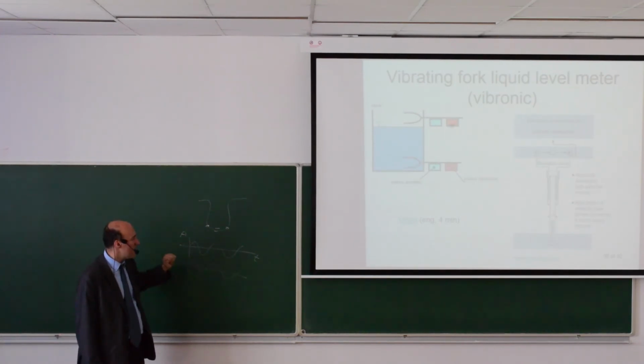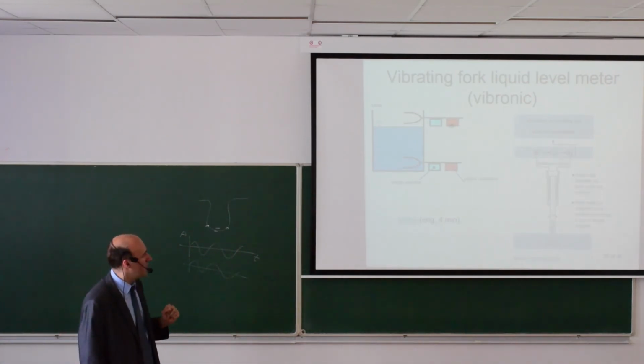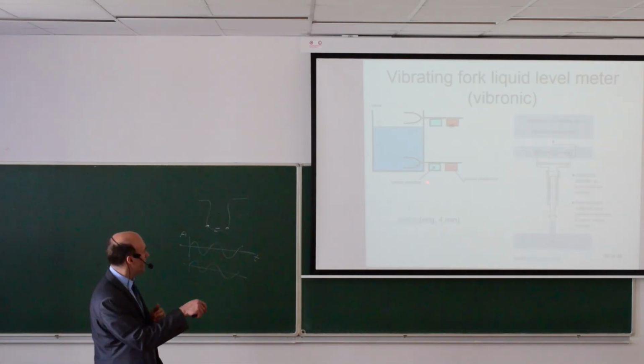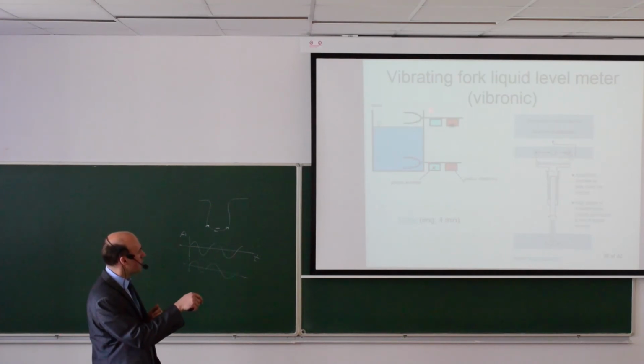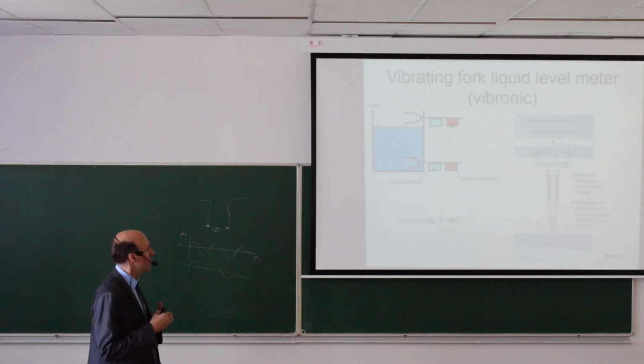What will happen here is that the resonance frequency of this vibration will change if the fork is submerged or if it's not. And you are looking for this transition, for this change in resonance frequency. So this is a typical arrangement.